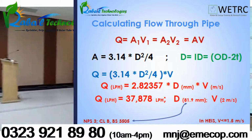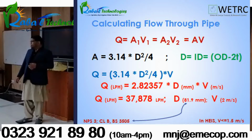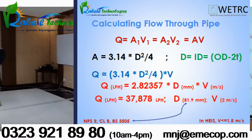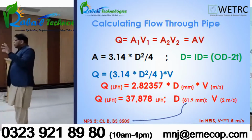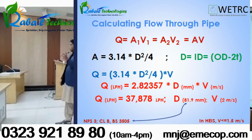As per the BS standard, it's around 88 millimeter. So 88 divided by 25.4 will give you around 3.5 inches. Actually the pipe is 3.5 inches, but we call it 3 inch. Similarly, a pipe that is actually around 2.25 inches, we call 2 inches. That's why we use the term nominal size.